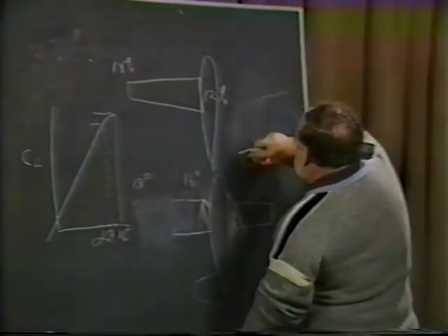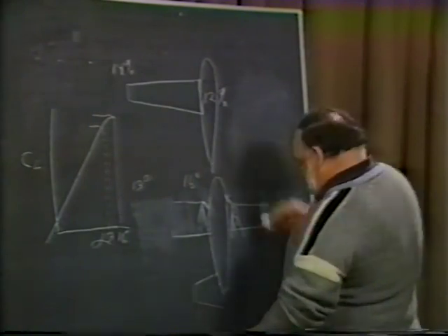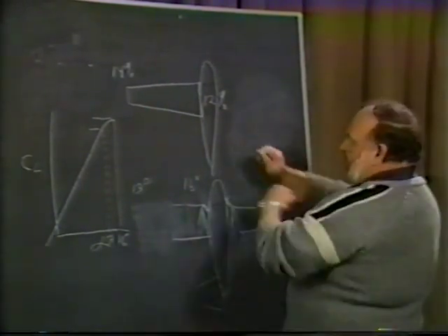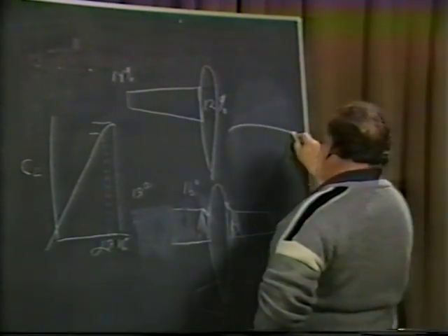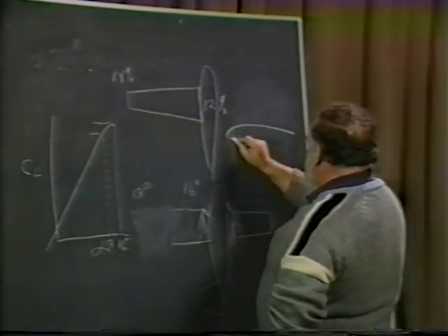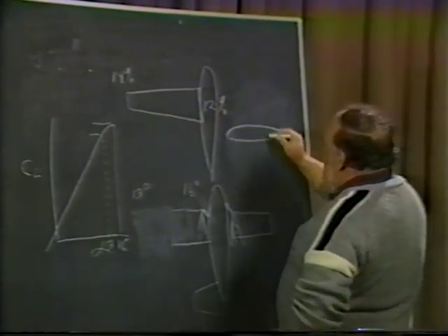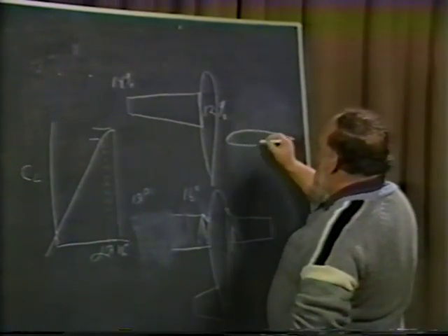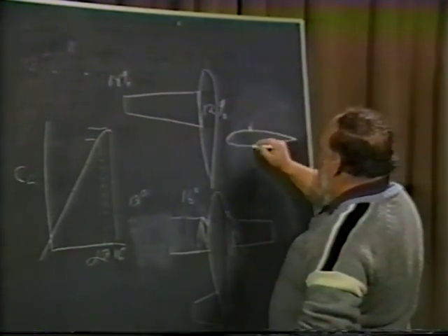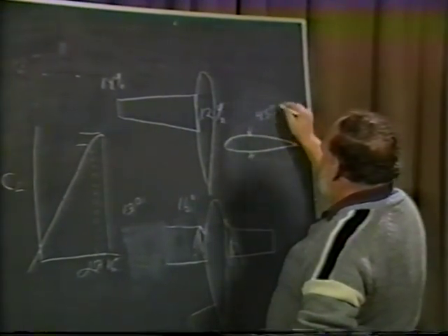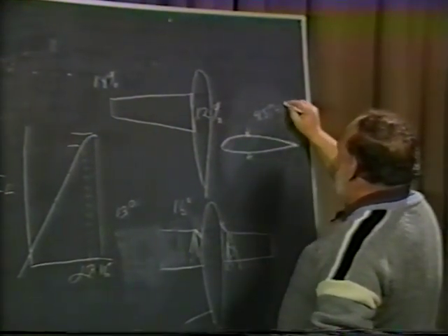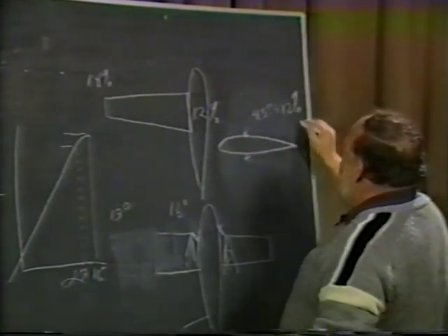let's draw it over here. Head-on view. I'm talking from a chord line view. If you would draw the inboard airfoil section, it was like this. So this thickness in actual inches, in this case I think it came out to be just about 4.5 inches of thickness, which at that point equaled 12%.